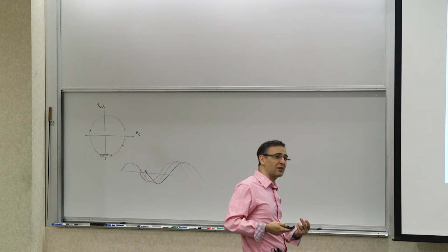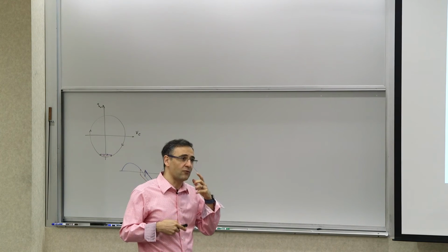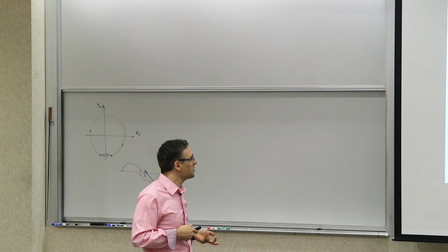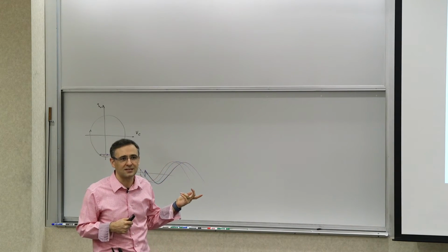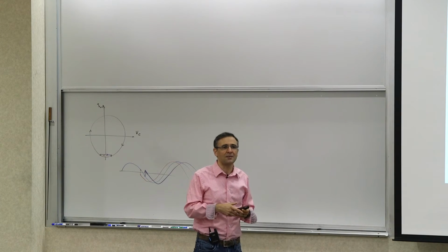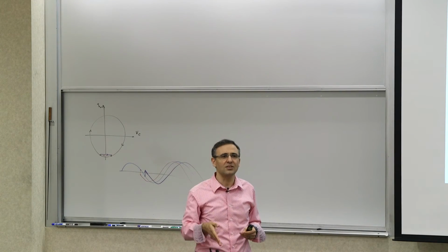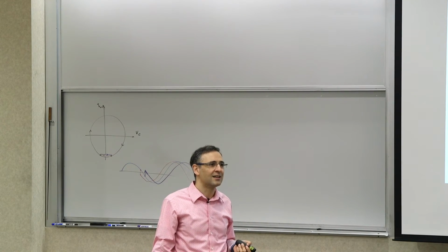Now, is this generally true? Is it true that for every oscillator, this will reduce the phase noise? No. Here's an opposite example. You remember in a ring oscillator, the transition time is the time where you have the maximum sensitivity, right? But that's when you have the maximum current anyway.